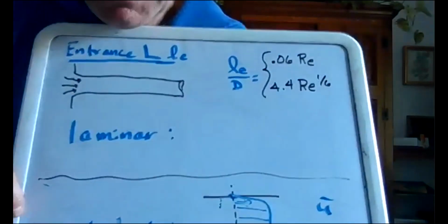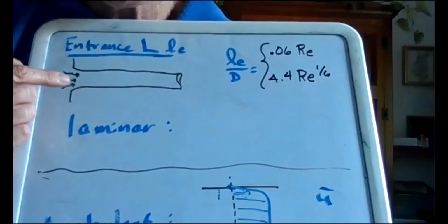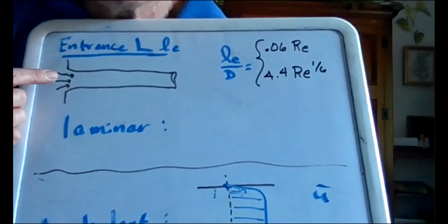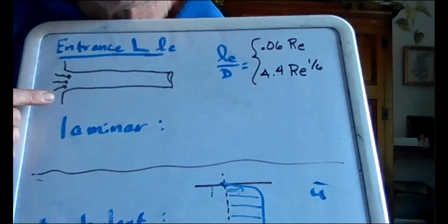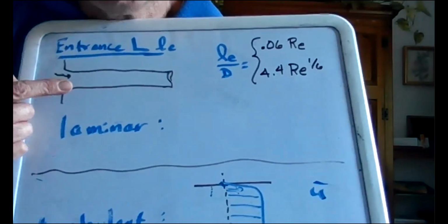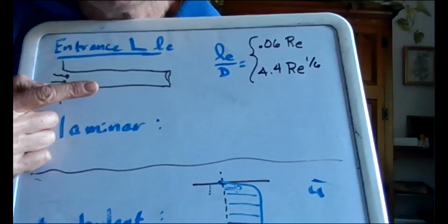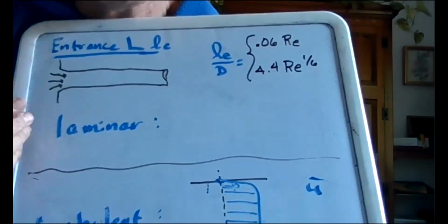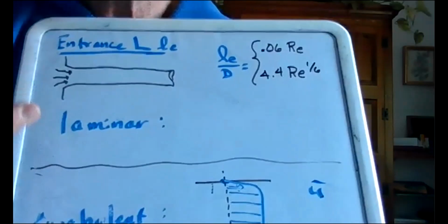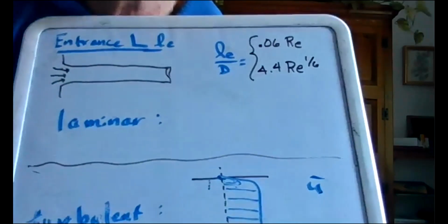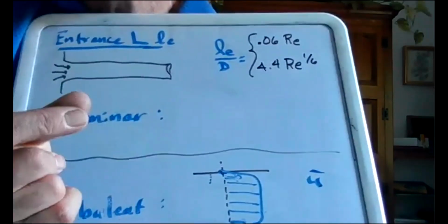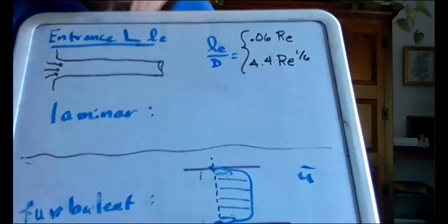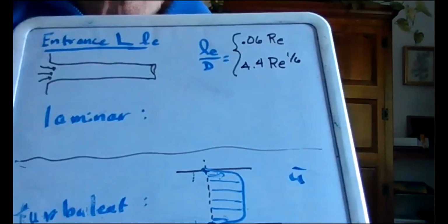But if you think about laminar flow, if this flow enters at a uniform velocity, say 0.2 feet per second across the whole pipe, the middle has to speed up, and the portions close to the pipe edge have to slow down because of viscosity. That doesn't happen instantaneously. Your car doesn't go from 0 to 50 miles per hour instantaneously. There's a transitional length, or a transitional period. So what distance is that transitional period?